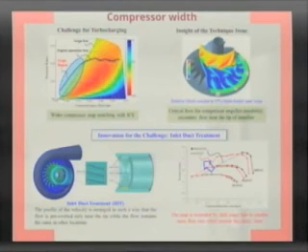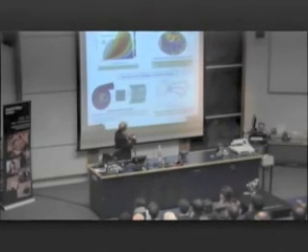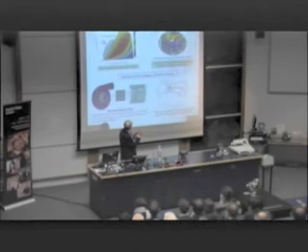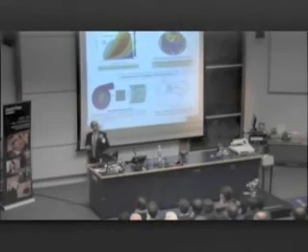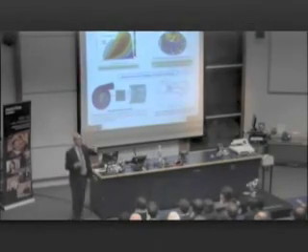You can't touch it, so you now redesign to ensure you're within that line. So we've come up with an innovation to be presented in less than a month's time, where we put what we call inlet duct treatment. We put some holes in the inlet there, aligned to some particular direction, and we target that flow into the regions of the leading edge of the wheel, where this surge event in this machine is shown to be promoted by the flow in that space near the tip and the inlet of the compressor.